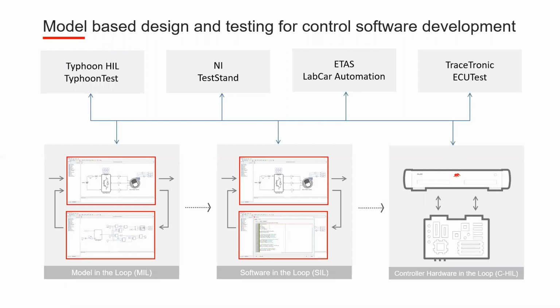So essentially, we see testing as a way to help us deal with the complexity in the controllers. If we use hardware in the loop, testing can become an integral part of the design workflow, and we can start using it much earlier in the process, even before an actual plant becomes available.